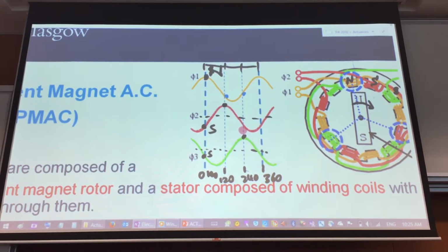So although your activation of your coil is at a certain speed, eventually when your rotor starts to rotate, it's actually 1 to 3% lesser than your activation of your coil speed. So it's because it's using magnet, it's not a gear system that will be moving that shaft in an absolute sense.